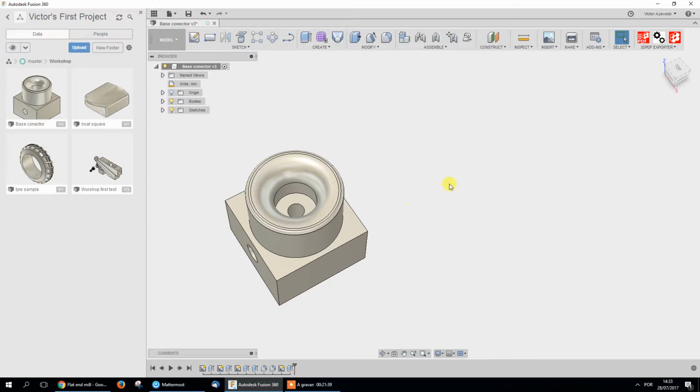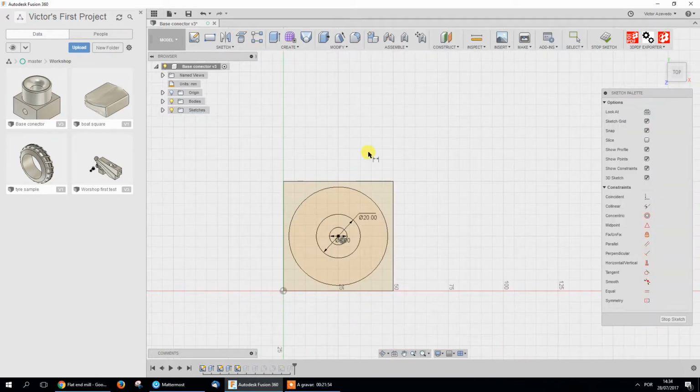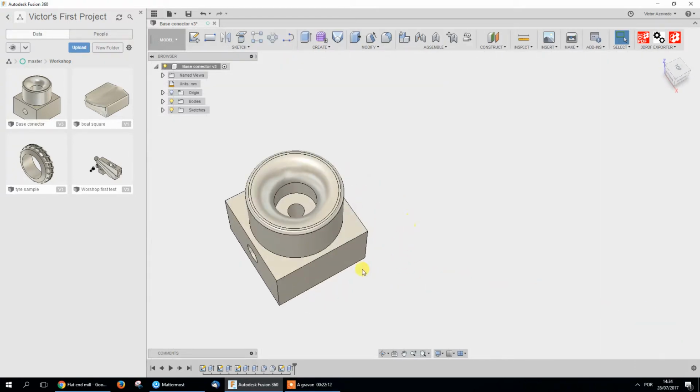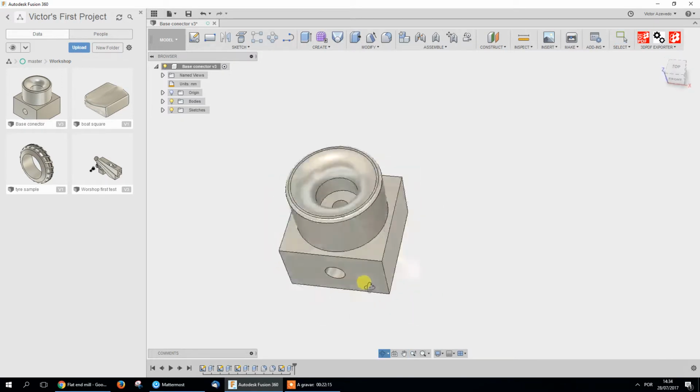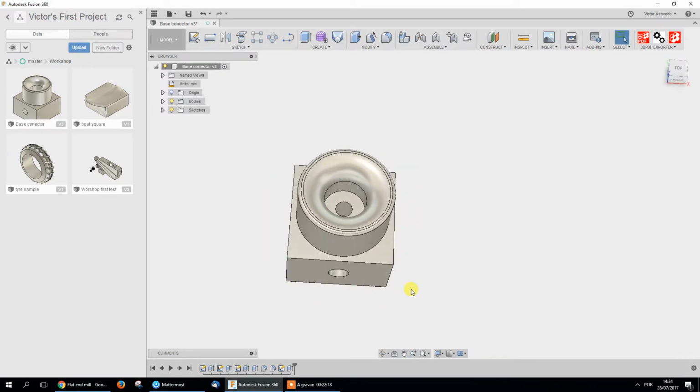Ricardo, what is not working? I don't have the option that has a D. It has to be in the sketch. You have to double click on the sketch, and if you click D, it will open this icon, and then you can use it on the line. You forgot everything from the morning. D for dimension, only in the sketch.